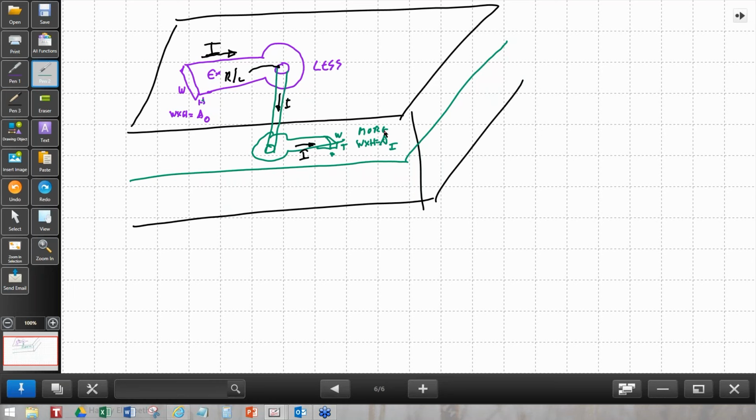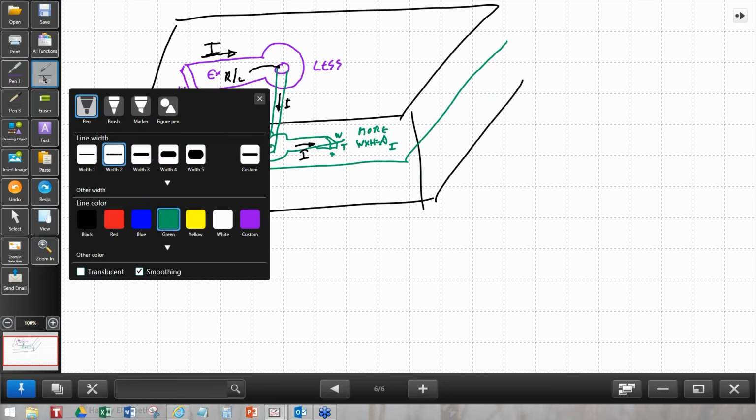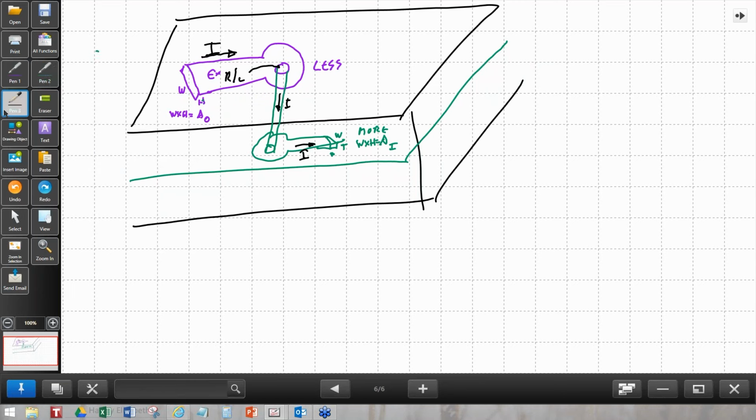Well, you could say, let's look at the barrel. If I look at the barrel, I'm going to see its cross-section. It has an OD and an ID, and I can take the area of the OD minus the area of the ID, which is equal to the cross-sectional area of the via. I can make that roughly equal to what it is on the top and the bottom if they're the same, if it's just carrying current. But if you're trying to dissipate heat, now you need to look at the various things.